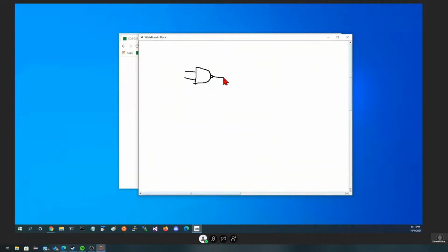We have 2 places we could hook the LED. One, we could put a resistor, and then have the LED sitting here to ground. The second case, we could have a resistor, and we could have the LED up here hooked to 5 volts.